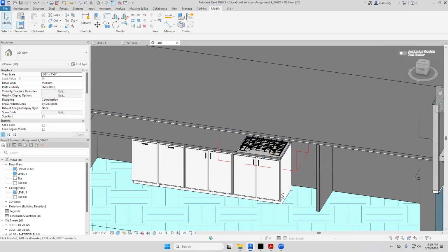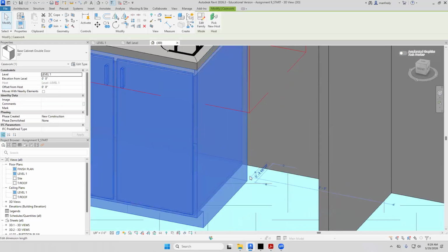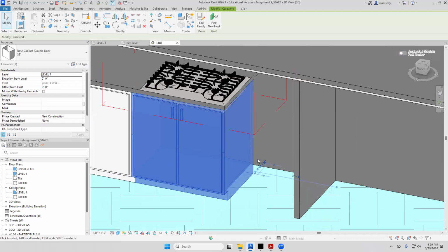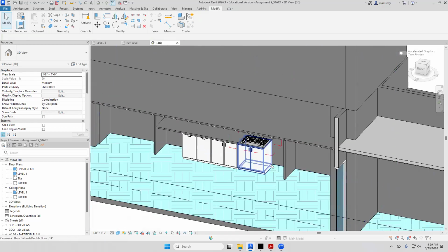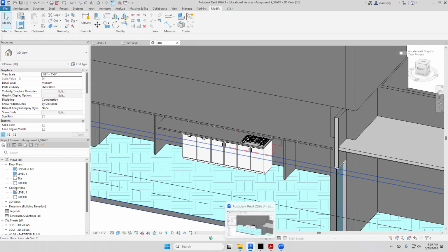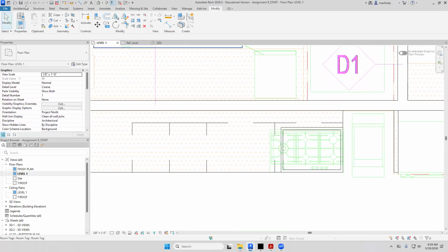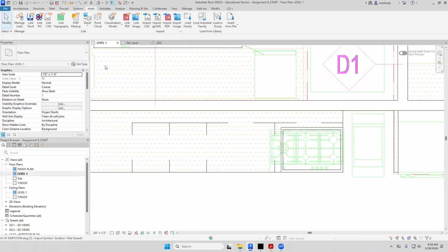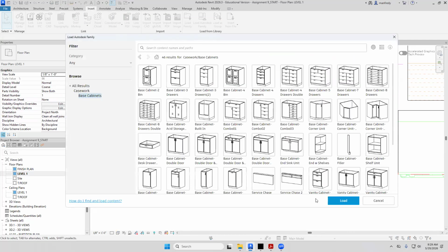And this is what you have. And you can see here, there's a gap between the back of the cabinet and the wall right there. And that's why they showed a double wall, a fake wall basically, back behind the cabinet to fill up that space, so you don't have this opening back there. You can also close that off. Revit has a family, let me see, I'll show you. Insert, Load Family. It's called a filler.